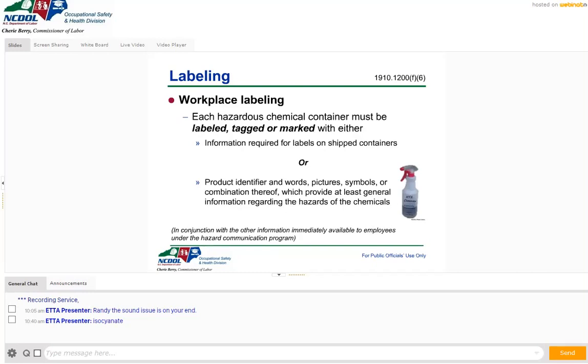Okay. And Trey says sometimes you can find the numbers in section 16 in the safety data sheet. So if you're using some of those labels that don't have those numbers on them, at least for those chemicals, I would be communicating those hazards differently, because I don't want to put an NFPA label or HMIS label on the chemical and have those spaces blank where the numbers go.